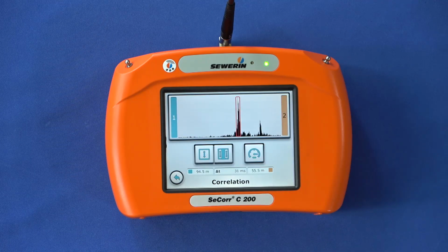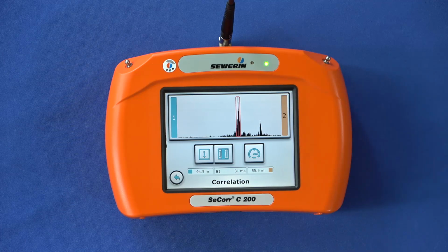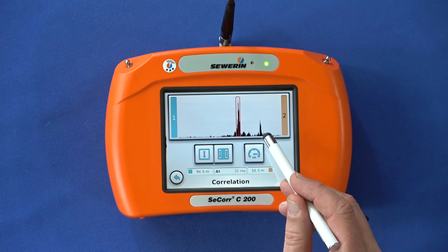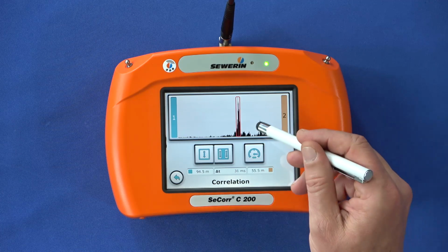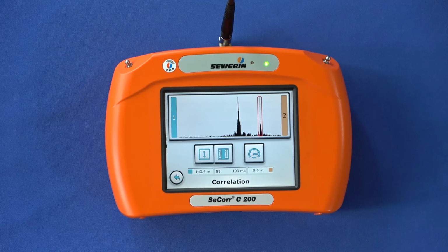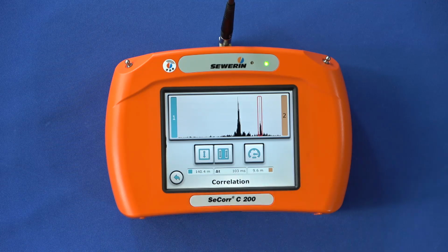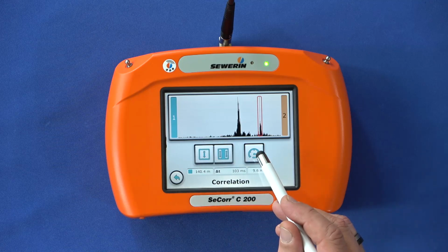You can now see the correlation function in the upper half of the display. This large display allows you to recognize smaller secondary peaks much better. You can now set a mark by tapping in the correlation, and you will immediately receive the associated data of the secondary peak in the results area. Two function groups lead to the optimization functions peak suppression and sound velocity measurement.